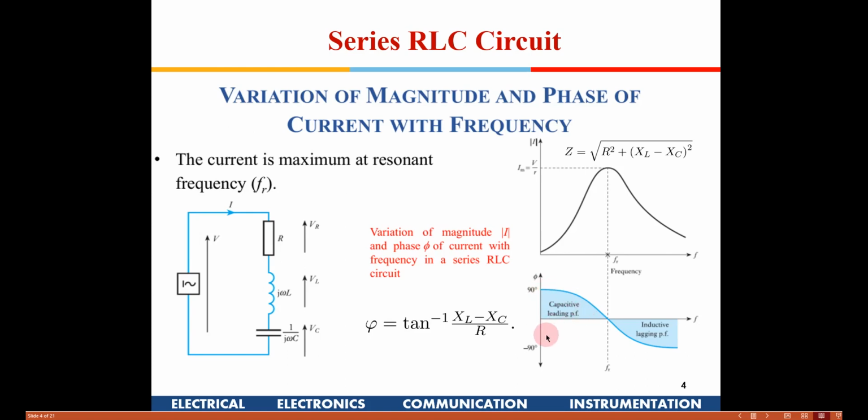As and when the frequency comes to the resonant frequency, there will be no phase difference, and then if it keeps increasing, the inductance will start offering a greater impedance, right? At omega equal to infinity, L omega will become infinity. Again the current will become 0.